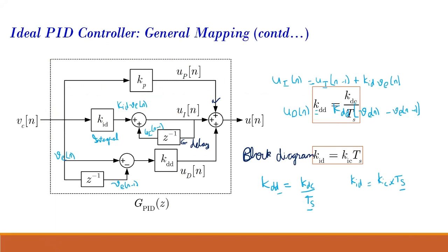Right. So now we will proceed. We will use these for understanding how we translate our continuous time gains to discrete time. If you would have seen in week 4, it was taught that a continuous time loop transfer function is equivalent to the discrete time small signal model transfer function, only we must include a delay in the continuous time.